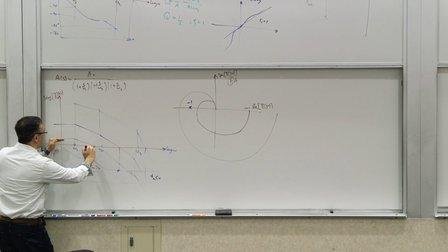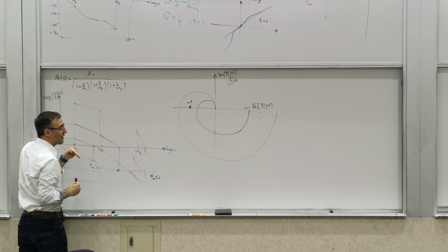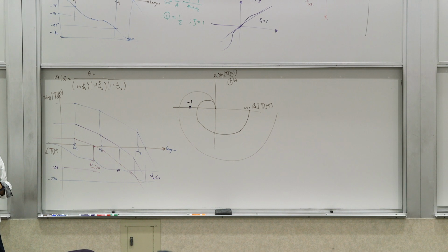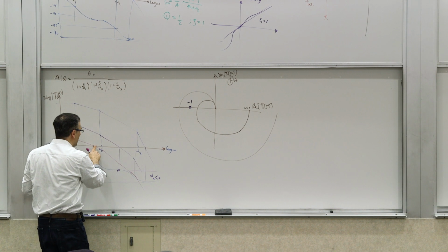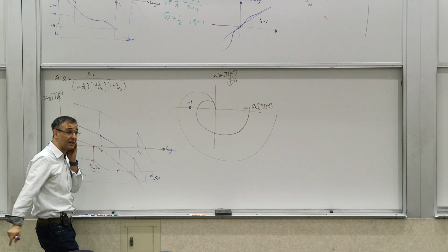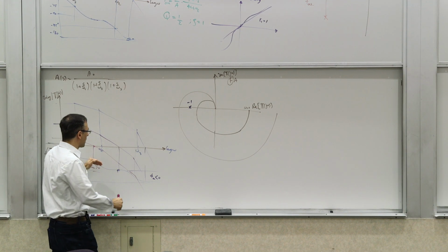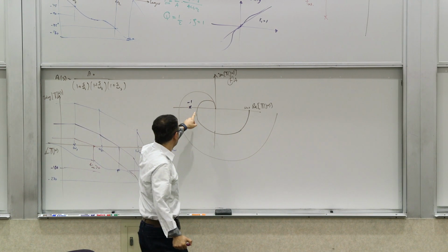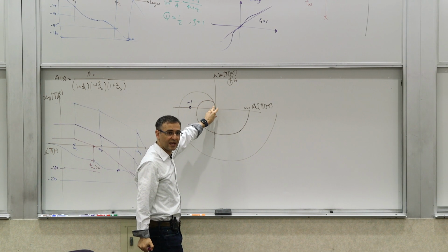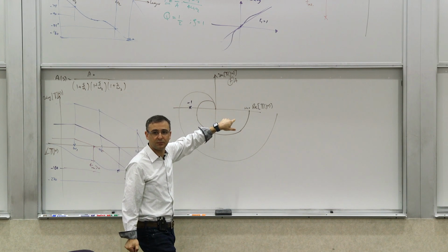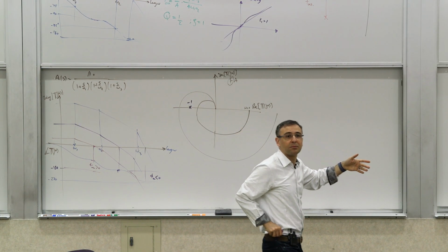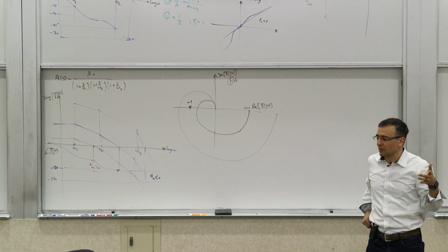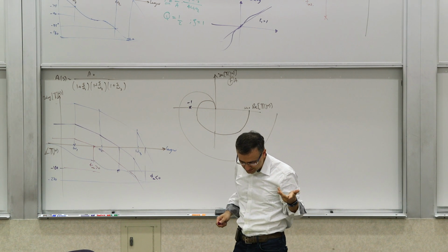As we increase f, we are moving to higher and higher values, which pushes the omega unity, the frequency at which the gain becomes 1, higher, which can then produce smaller and eventually negative phase margins, which is also consistent with this picture. As you scale this up, you start encircling point negative 1, and then you are not stable. So these pictures are consistent.